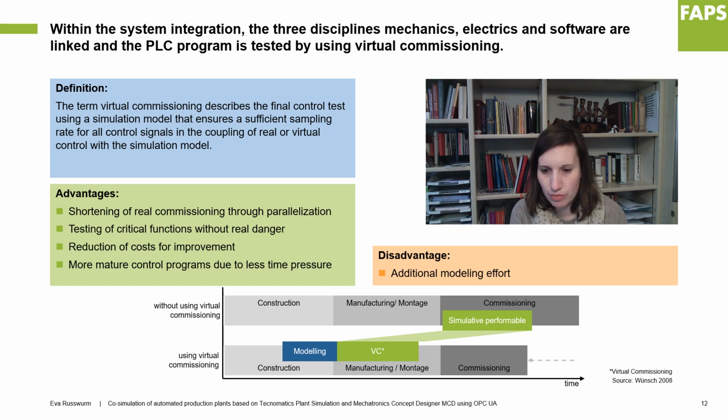There are three types of virtual commissioning: model in the loop, software in the loop, and hardware in the loop. The testing is always performed on the model, not on the real existing plant. The aim is therefore to model the model as realistically as possible. The terms model, software, and hardware in this context refer to the form of the control that is used here: control within the model, control by a simulated PLC via PLC Sim Advanced, or using the control as a hardware component.